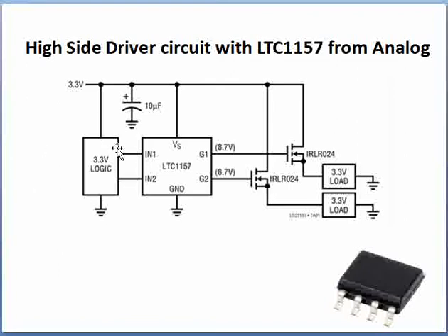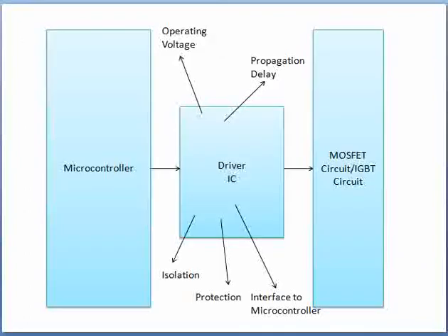3.3 volt logic. 3.3 volt logic will be from the microcontroller. So this is just to give us an understanding of how the driver is going to control. And then ultimately, while we talked about the driver, we need to know what the specifications are, how we need to control all these, right? So the first main point is, when you select a driver IC, you have to select a driver IC which is within the operating voltage, and then how you interface to the microcontroller is another important point.